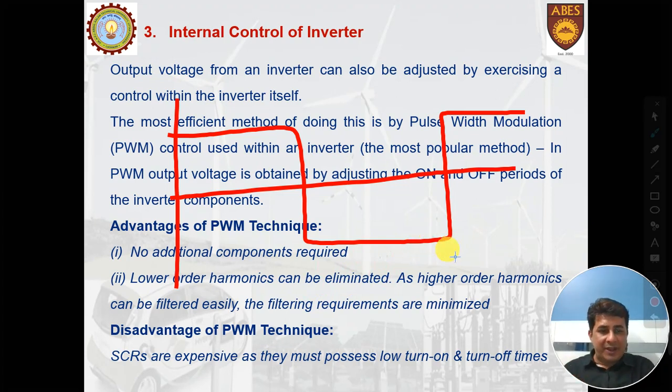Like if you are running a fan on an inverter that is not sinusoidal, there will be a sound through that fan. Why is that humming sound coming? It is because the inverter you have used contains harmonics, and the devices produce the humming noise.